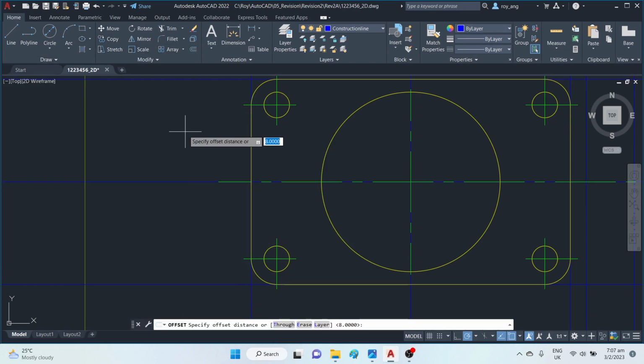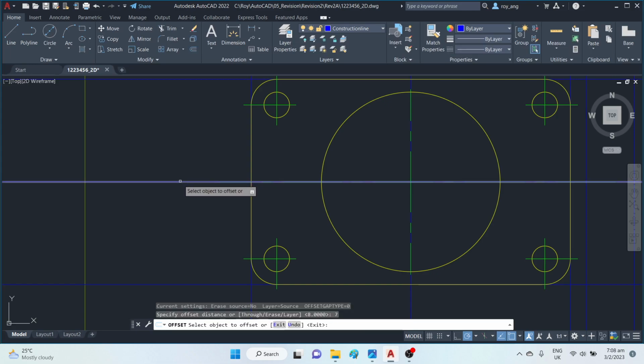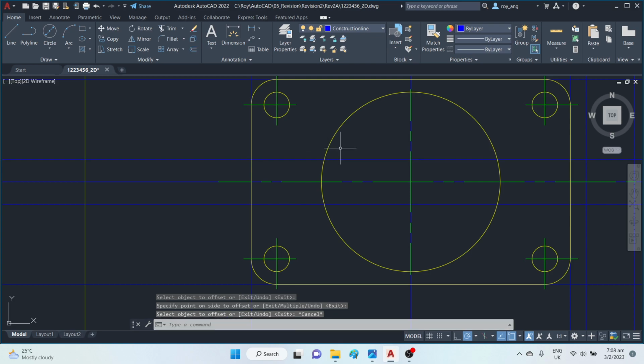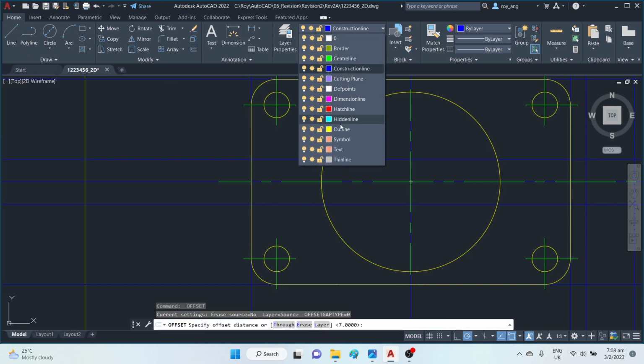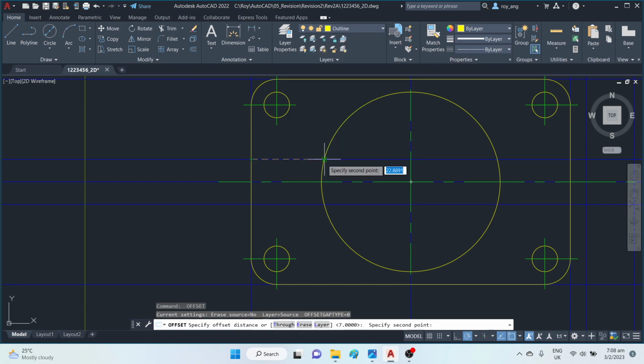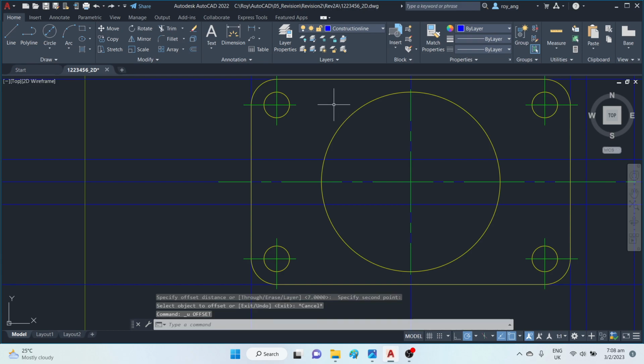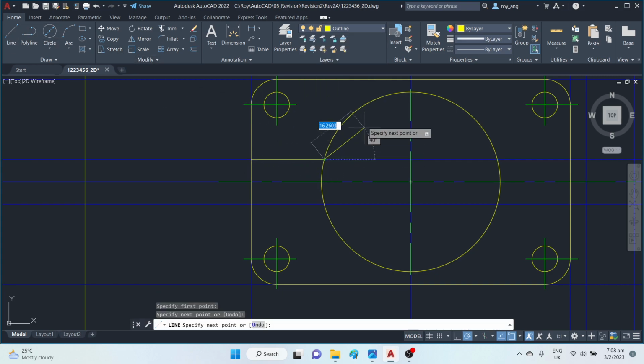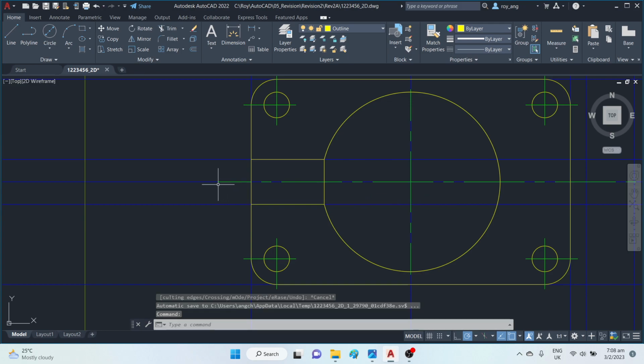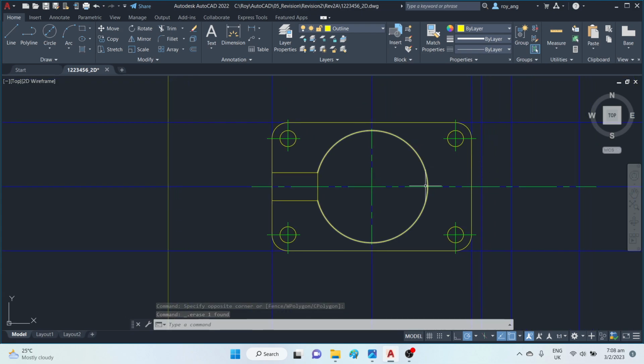And what I'll do now is I'm going to offset, I'm going to draw the rib. The rib is 14 millimeters in width, so it's 7 on each side. Alright, and then what I'm going to do is I'm going to draw it out. Oh, through that. We'll go to our outline, line type. I'm going to draw my rib, and then I'll do my trimmings. Okay, I don't need this anymore. This is for my rib. Now don't bother about the cut, we'll trim that later. We'll go about with all the circles.